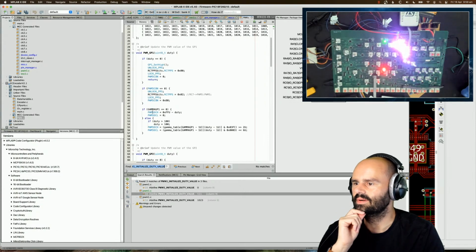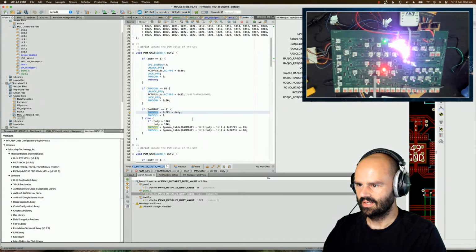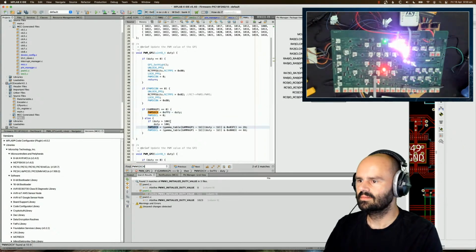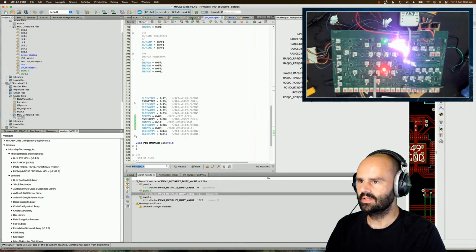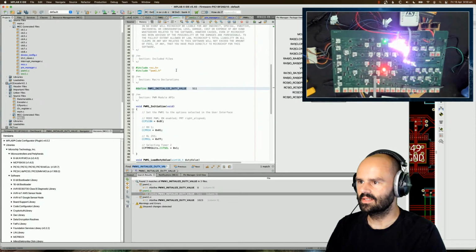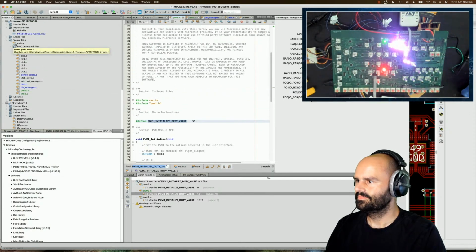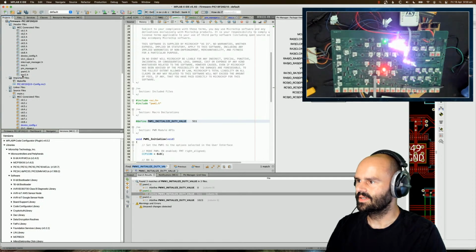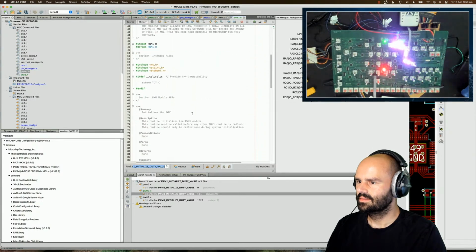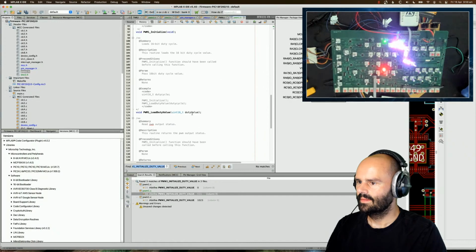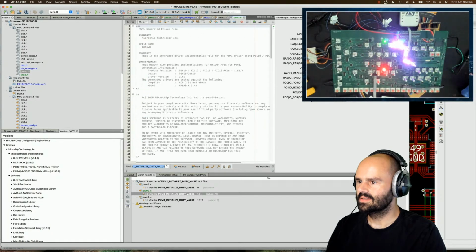It's got a PWM 5 duty cycle high, duty cycle low, so these must be right. So we need to find where that parameter is in our set of code here. Maybe up in the headers here, MCC generator files, pwm.h, pwm initialize, output status.